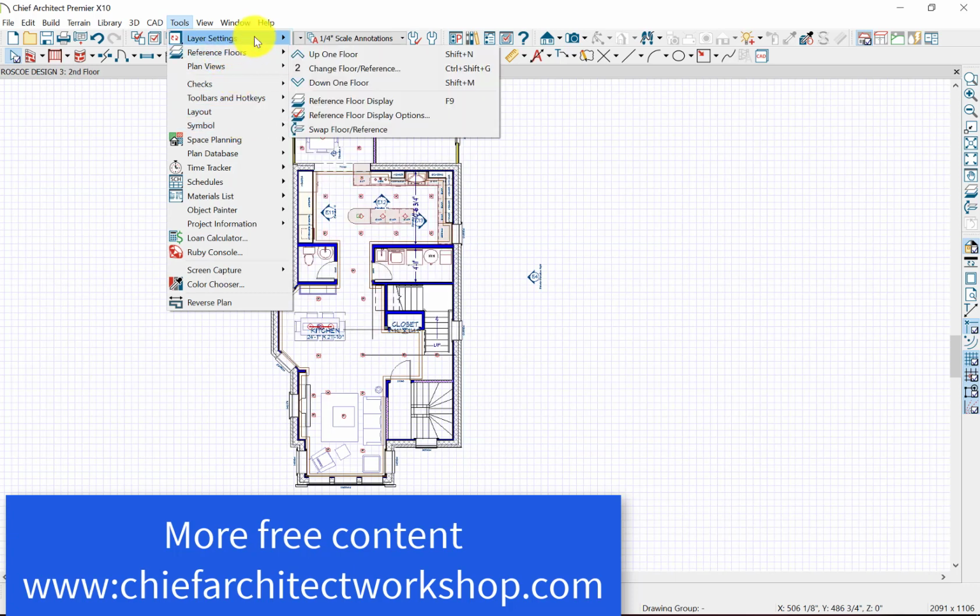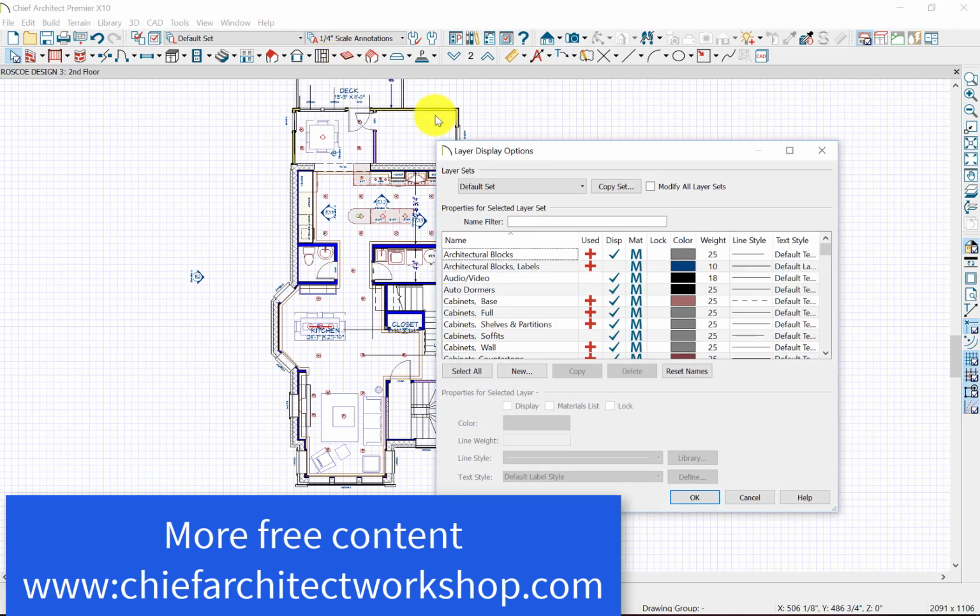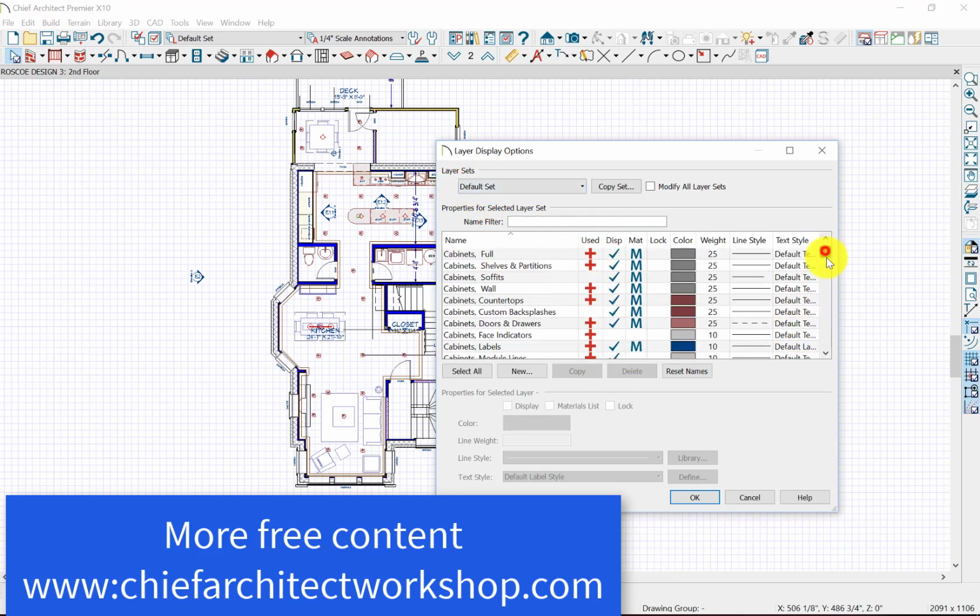So let's start with our layer settings. Display options. What this does is displays the various layers on whatever it's called, like the default set. You can turn on and off layers. Very useful tools every once in a while. If you're trying to click on something and something always gets in the way, you can find out what layer it's on and lock it so that you don't keep on clicking on it all the time, and that's useful as you're drawing.